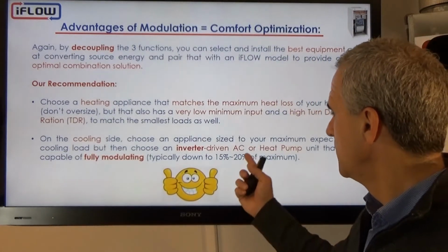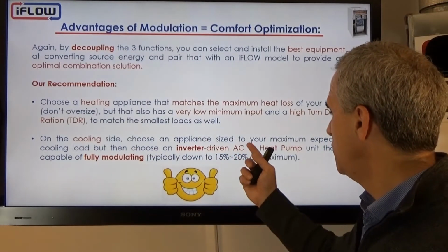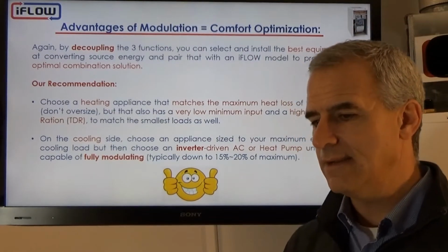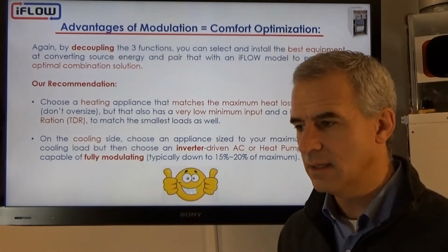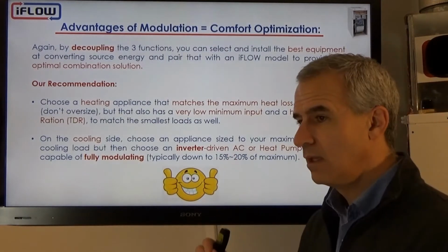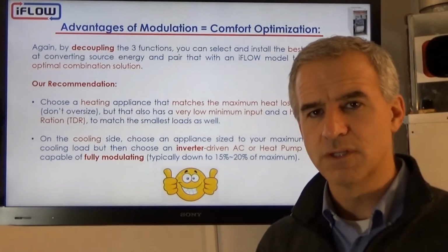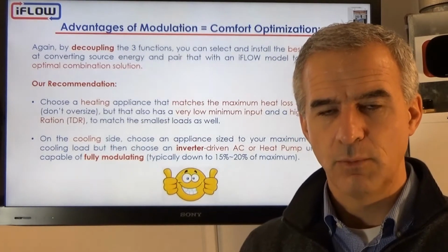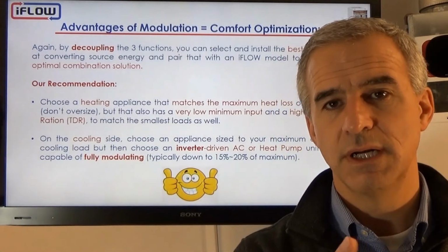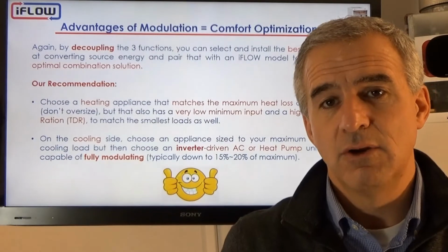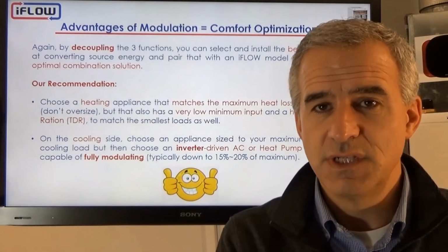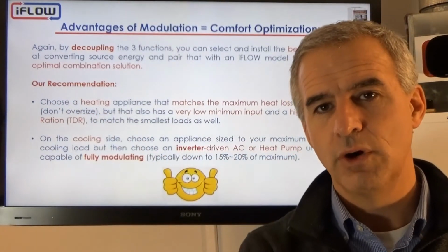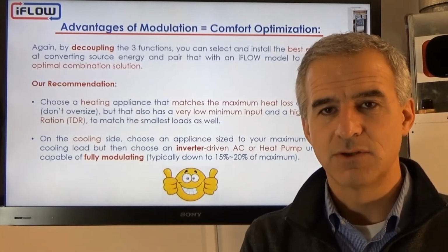So on the cooling side, you want an inverter driven if you can. So again, a single stage or two stage will be cycling. On the electric side, there's not as much loss on the cycling side, but you have the issue if your equipment is oversized, then you're going to have issues with freezing your coil. When you're delivering, let's say, too much refrigerant to the coil, or if it can only deliver at maximum, or let's say two stage at 70%, it's going to deliver that refrigerant in. If you don't have the air volume going across that evaporator coil, it's going to start to freeze up.